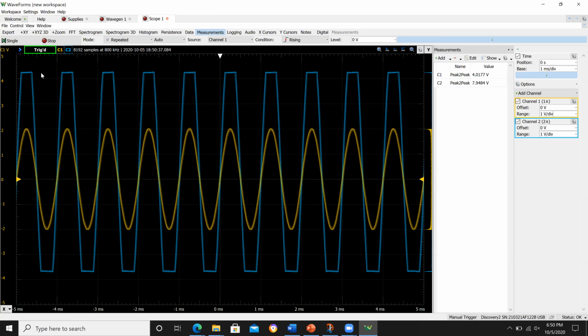Why is that? Well, a couple of things. First of all, let's go back and talk about our supplies. Our supplies are limited to 5 volts and negative 5 volts. Those are our rails, right? Well, probably the first thing you're going to notice is, yeah, this is called clipping. So we're not getting a perfectly gained up version of the signal. It's going flat and it's limited by something, right? At the top and bottom.